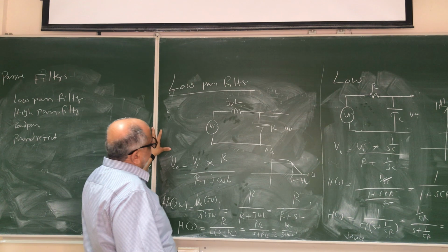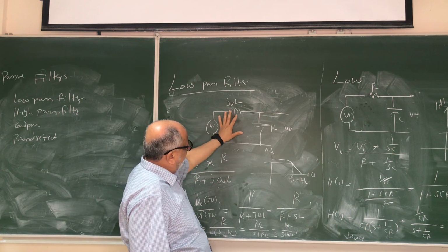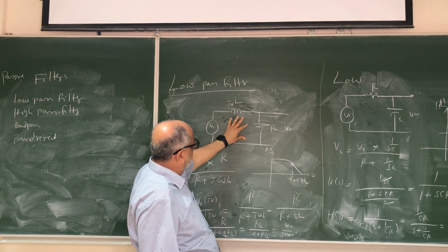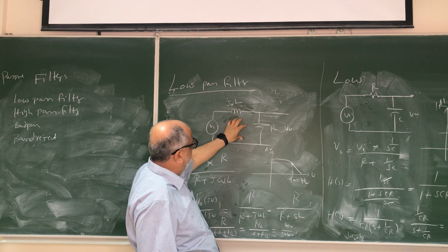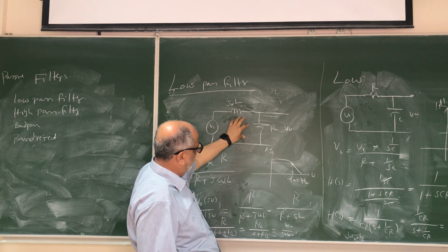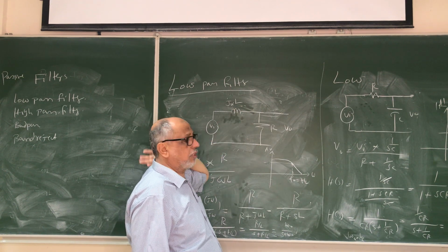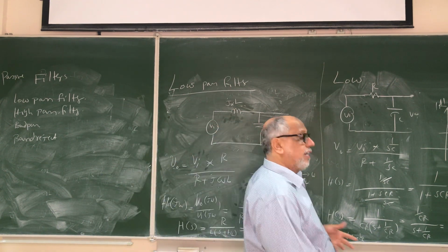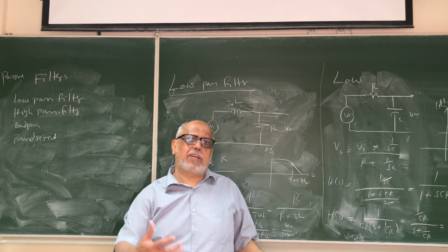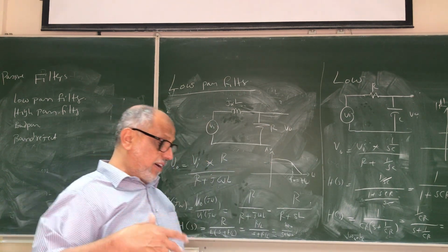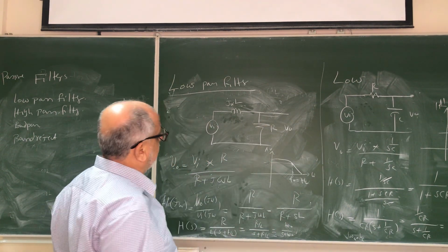Now, the disadvantages of these filters: the maximum gain you can get here is 1, so you cannot have more than unity. So there is no gain actually. The maximum is unity. Okay, that is one drawback. And let us assume I want a filter and at the same time I want to amplify the signal. Then we cannot use a passive filter for this.